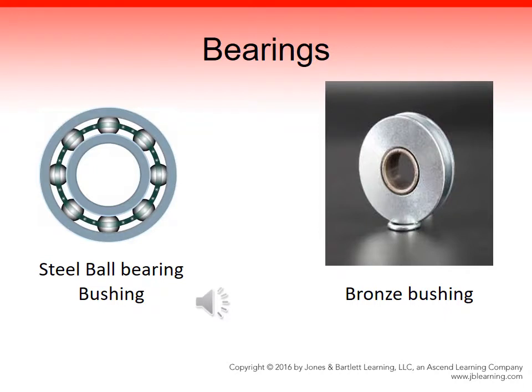Most pulleys for high-angle work have one of 2 types of bearings, either bronze bushing or a ball bearing. Bronze bushing pulleys are very strong. They can be taken apart to be cleaned. They're less expensive than a ball bearing, but can also be contaminated by dirt and grit.